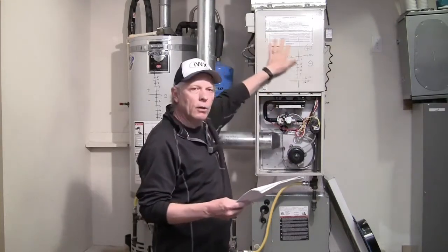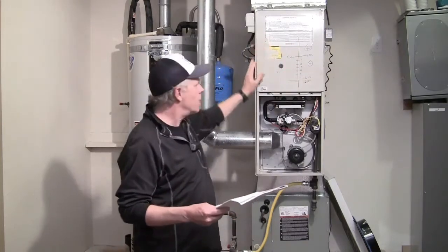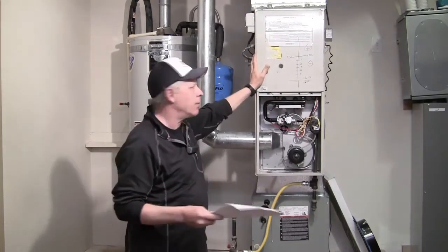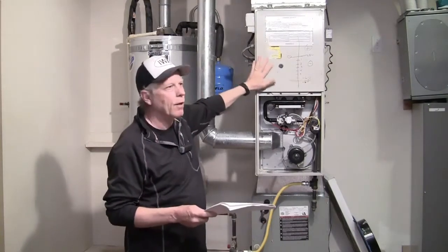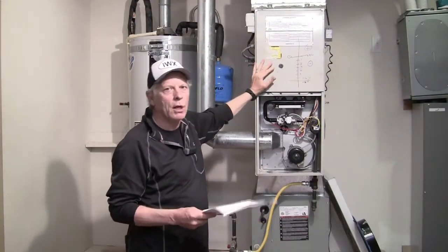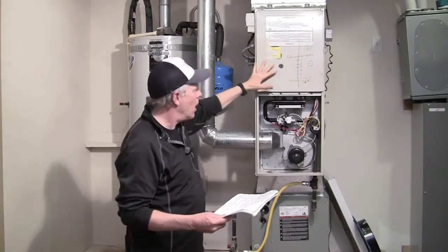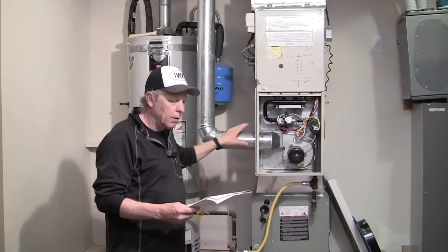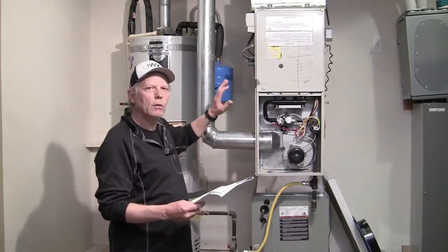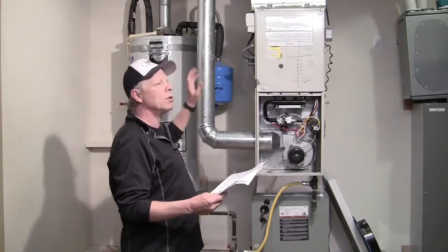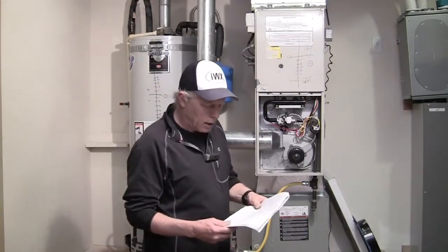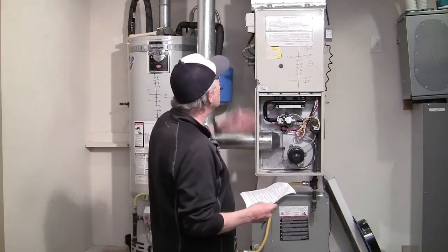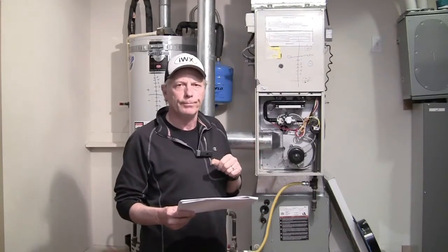Missing air handler doors. You know, the air handler door here we've basically got it taped on right now. Why is it taped on? Well, because we take it on and off all the time. But if that was missing, that's a big return leak in the combustion appliance zone. Excessive corrosion of the chimney, it could be an issue with a heating system. Disconnected chimneys, loose chimneys, chimneys too close to combustion sources. Return leaks to the attic, return leaks to the crawl space. So all those types of things are health and safety concerns for a heating system.